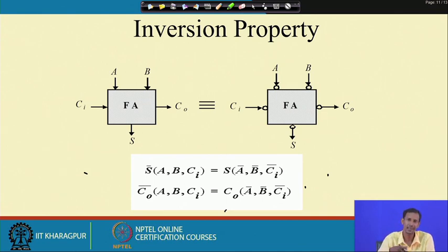If you just see the transistor, that means NAND gate level implementation, at that time you have to put one inverter at the output, as the operation is coming as NAND operation. I need AND operation. So, I need one inverter at the final output for making the NAND into the AND.